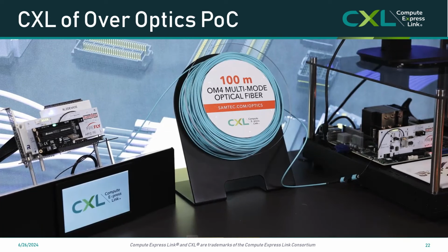As a matter of fact, the first time that we showed our CXL over optics proof of concept was at Supercomputing 2023 last fall. Basically, what you see in the illustration here on the right-hand side, we're using an AMD Genoa platform, which has native CXL support. Samtec designed a PCI Express form factor add-in card with our PCI Express / CXL over optic transceivers. You can see on the right that we started with a x8 configuration because there are 2 modules. This actually is x4 because you can see one transceiver here and another transceiver that they can plug in.